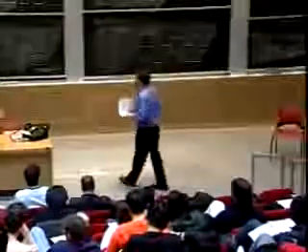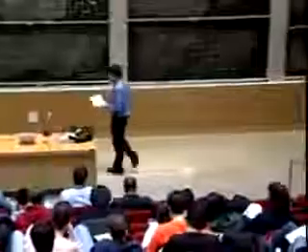So we halve the number of bits that we can send over the channel, because instead of a 1 simply being a high and a 0 being a low, now everything is both a high and a low. So we halve the amount of data that we can send on the channel, but we get this win that now the phase lock loop can actually work. It turns out Manchester encoding is actually commonly used. There are other encoding schemes that are less wasteful of channel bandwidth but operate on the same principle, trying to introduce extra transitions when possible.